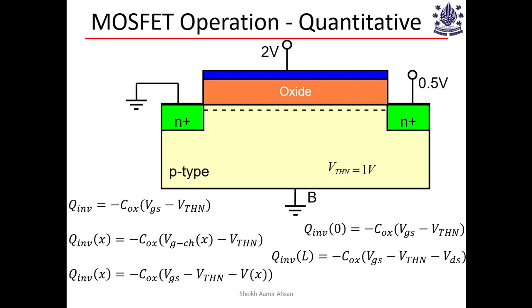One important point that I want to mention is that here I've totally ignored the voltage drops happening at these contacts, drain source contacts, right? Because this point in the channel, even though it is not exactly the source, the voltage here is taken as the source voltage, because I said that these are heavily doped, and therefore we'll ignore all the drops that are happening within these contacts.